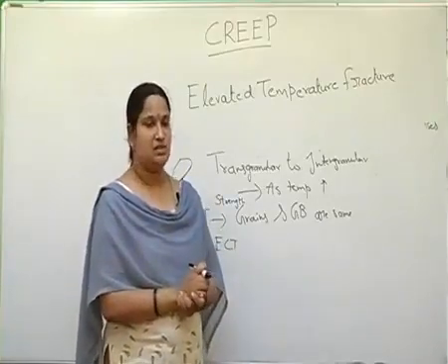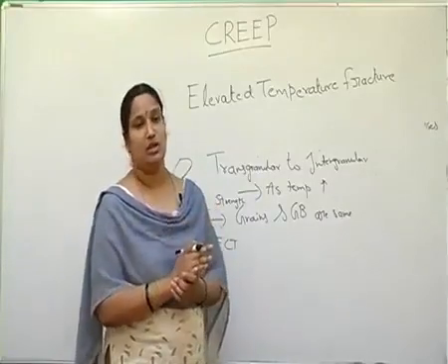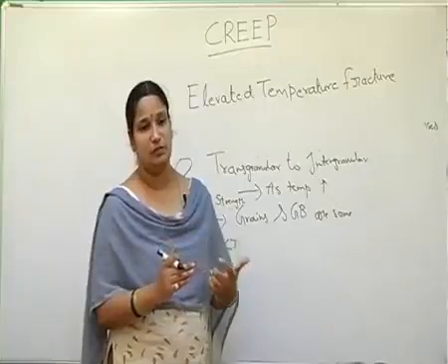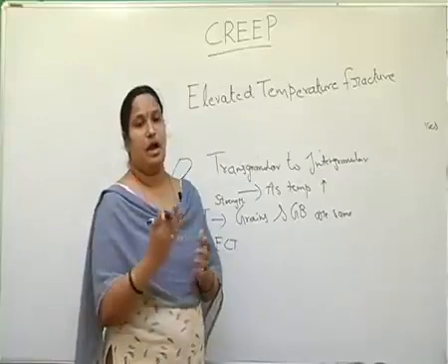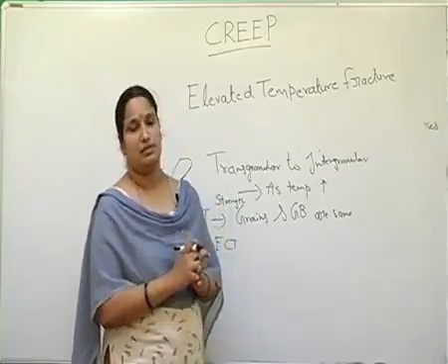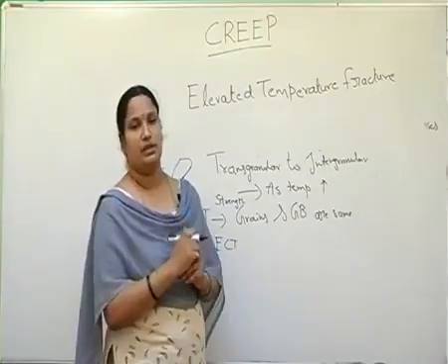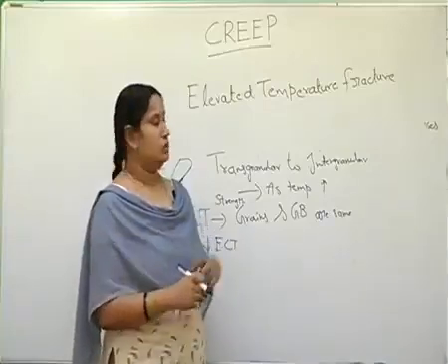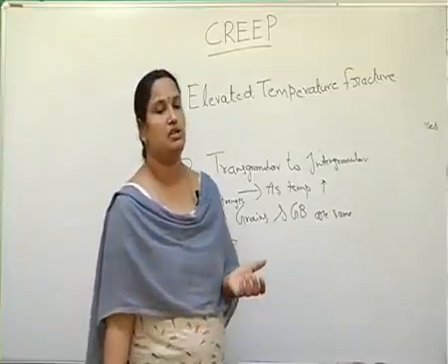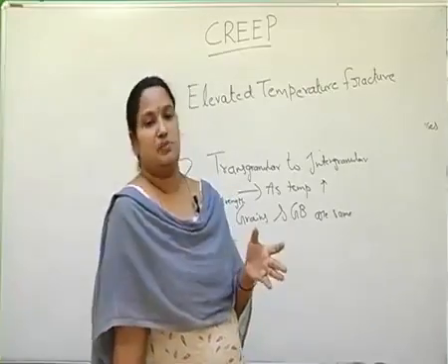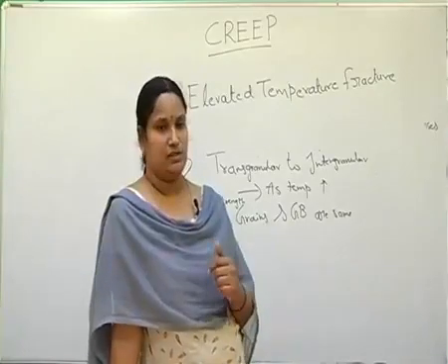Ductile fracture indicates that a certain amount of plastic deformation takes place, some amount prior to and after fracture. In the case of brittle fracture, there is no appreciable amount of plastic deformation that accompanies the fracture. So depending upon the temperature, stress, composition, and microstructure, stress rupture failures may be either ductile or brittle type of fractures.